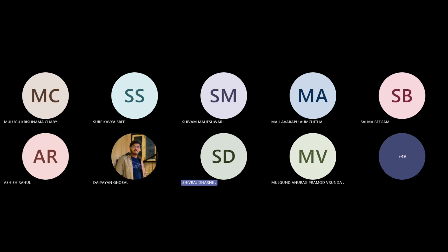So what we do in N plus 1 is put one extra backup unit. N is the bare minimum unit required. N plus 1 means one extra. 2N means two times. Suppose N means 1, then you have 2 times. The capacity required to run plus one additional backup component is N plus 1. Correct. I hope you understood it.